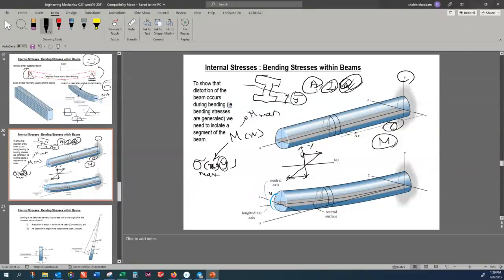All right, so I'm going to give you a formula. That formula is the first important equation for your final exam. In your final exam, there are two important equations. One of them is called the flexural formula. The flexural formula is how this normal stress is calculated. My normal stress due to the bending is proportional to the bending moment. The larger the bending, the larger the stress.